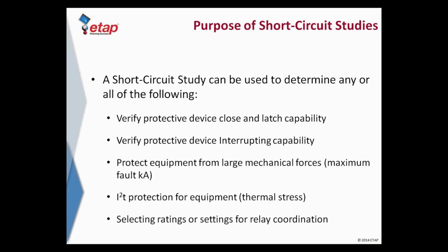So a short circuit duty study will be used to determine the following: you want to verify protected device closing and latching capability. You want to verify protected device interrupting capability. You want to make sure that the equipment is properly sized so that it can endure mechanical forces from the peak currents. You also want to make sure that it can withstand any thermal stresses, or I squared t. And you also want to verify your relay coordination, so you would need your minimum short circuit for coordination.